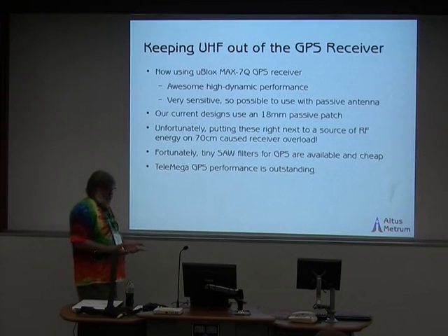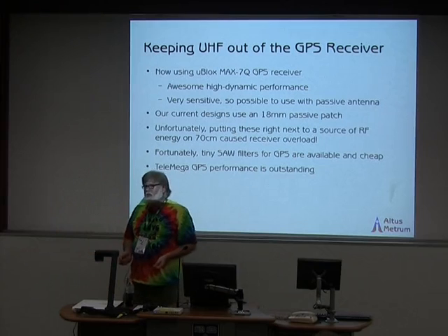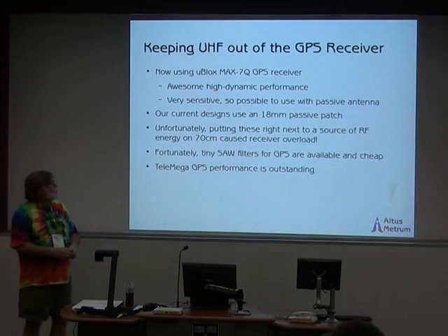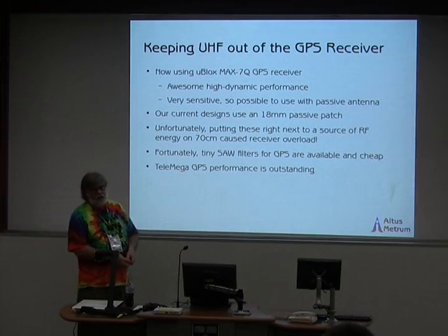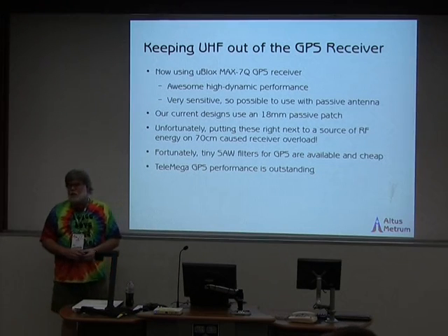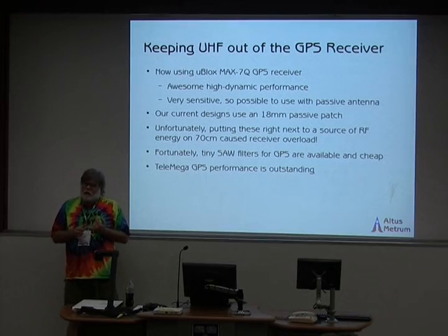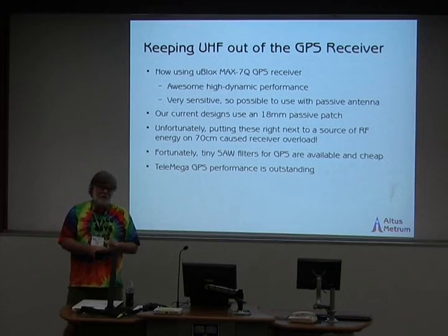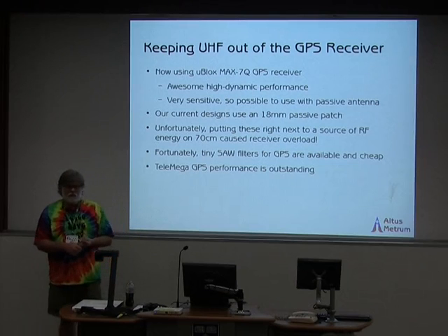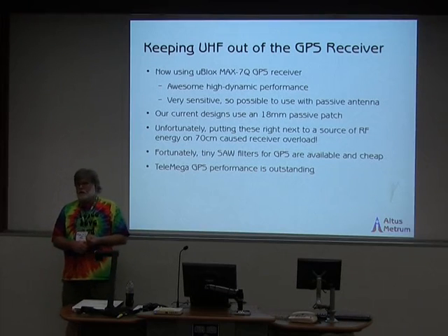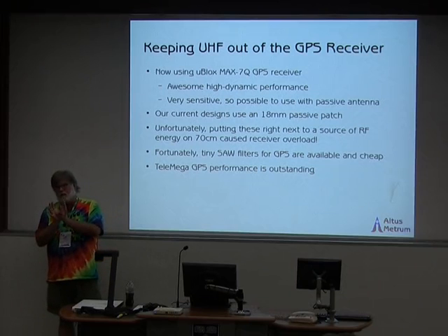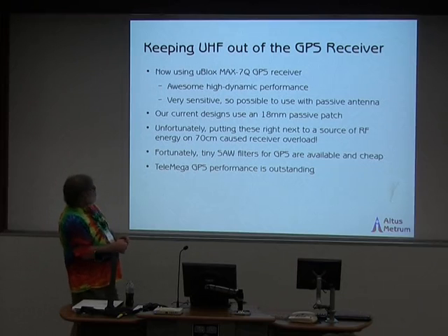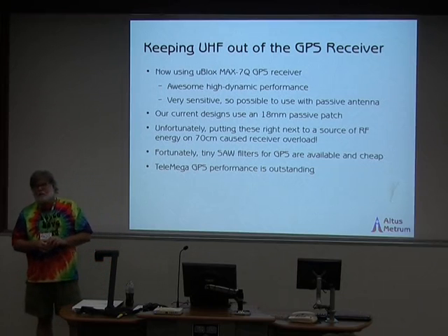As you notice, we have GPS receivers and UHF transmitters very close to each other on the same board. It turns out that with the SkyTrack parts, this wasn't a huge problem because we were using an amplified patch antenna. The more recent amplified patches we were buying actually had a SAW filter built in, so they were really only amplifying a narrow range of frequencies around the GPS L1 carrier, and we're doing a pretty good job of knocking down interference.